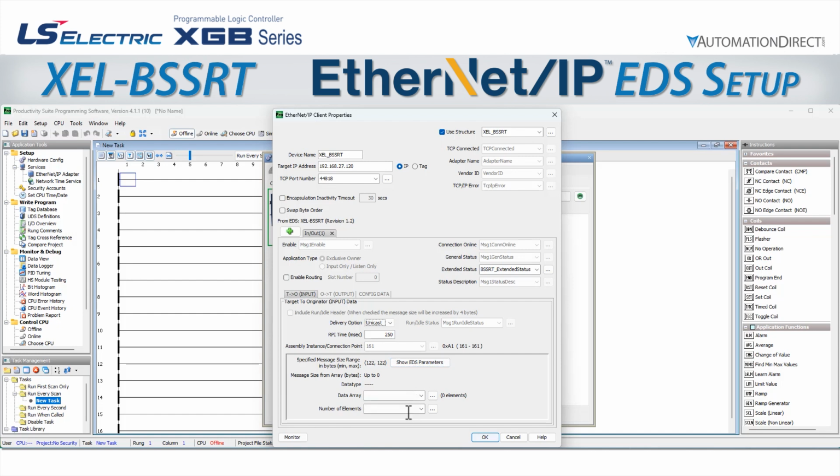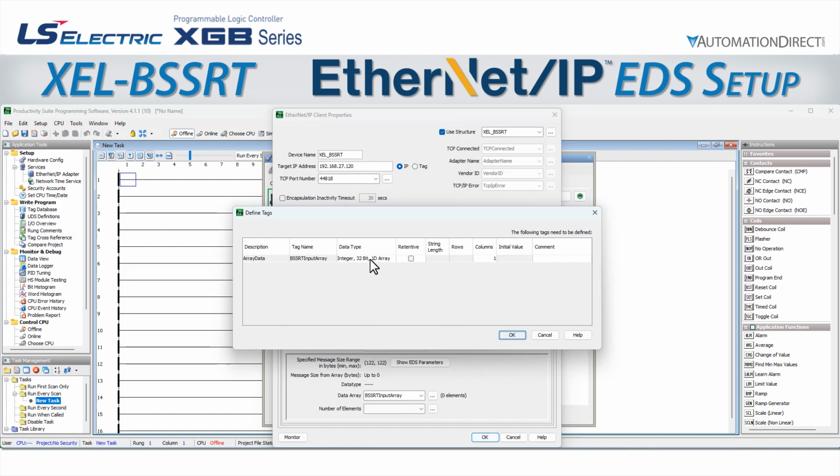That just leaves the data array for the input information. The BSSRT uses a minimum of 16 bits for each input or output data section, so we can use a 16-bit word array for the data processing. Since our input is set to be 122 bytes in the EDS file, we know we will need a word array of 61 elements, as 122 bytes is 61 words. We will name our array BSSRT Input Array. Productivity will then prompt us to create this tag array before moving forward. We will leave it as a 1D array of 16-bit integer with 61 columns. This will create 61 word elements, accounting for the 122 bytes of input information.